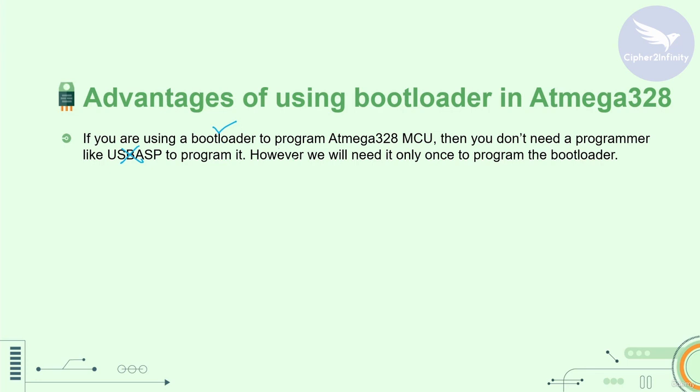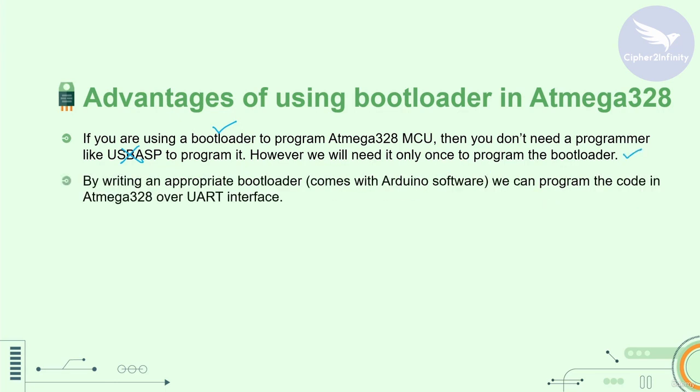However, as I told you, we need this USB ASP programmer only once to program the bootloader. The second point is, by writing an appropriate bootloader code, we can program the Atmega328 microcontroller over the UART interface.